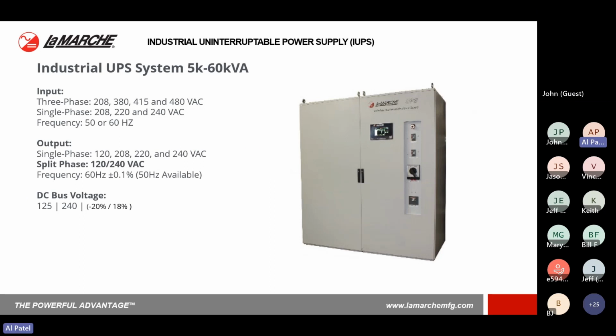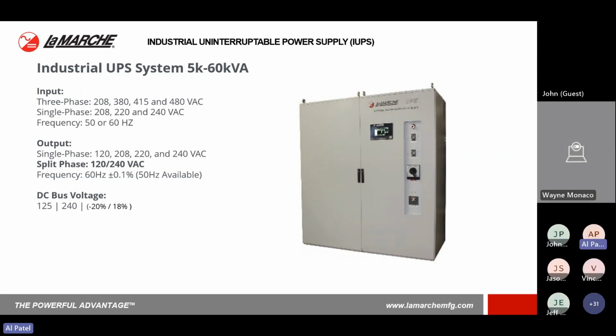The industrial IUPS comes in a 5K to 60 kVA output rating. The input can be powered from a 208, 380, 415, or 480 three-phase input. We also offer a single-phase input option, which is 208, 220, or 240 VAC with 50 or 60 hertz input. The output, we have a single-phase output, 120, 208, 220, or 240. We have recently also introduced the split phase output option, which is the 120, 240.